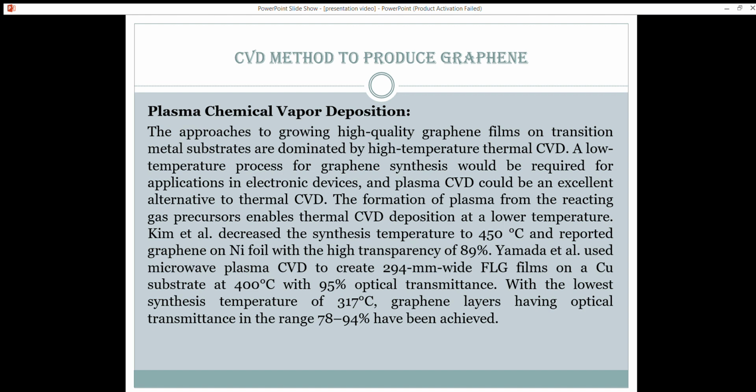Chemical reactions are involved in the process which occur after creation of plasma of the reacting gases. The plasma is generally created by radio frequency, alternating current frequency, or direct current discharge between two electrodes, the spacing between which is filled with the reacting gases.